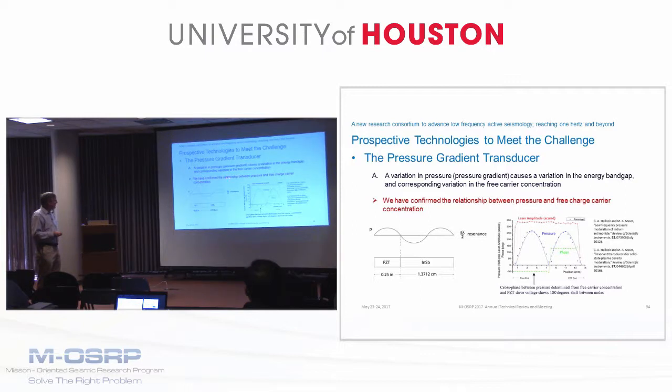So we have confirmed the relationship between pressure and free charge carrier concentration. The way we did that is we built a structure here of indium antimonide and a PZT to drive a single wavelength standing wave pattern in the InSb. And it turns out that you can use a laser diagnostic to directly measure the free charge carrier concentration.